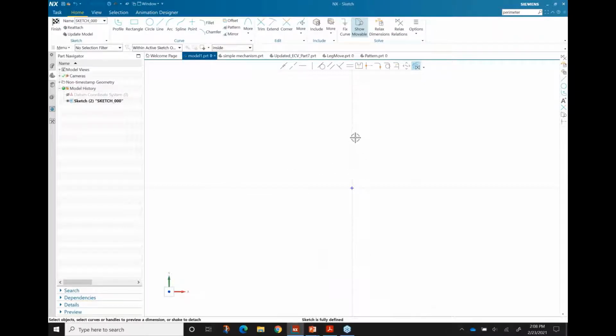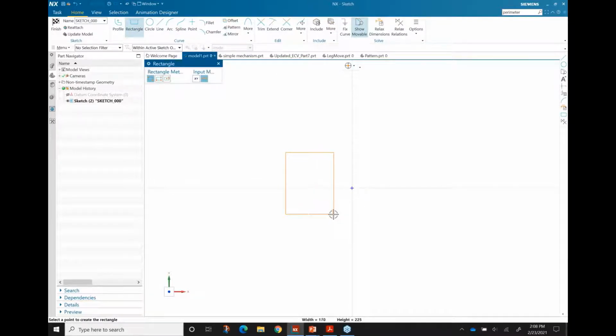Something else that's nice is you'll notice we lost the Y and the X axes. That's because they're replaced by this horizontal sketch axes, and it goes to infinity. I mean, you all remember when you would try to tie back to that little axis that was here, you'd have to wait for the 3 dots, try to get everything to line up. It was a pain, not any longer. So let's go ahead and just sketch a really simple object. We're going to just sketch a box.